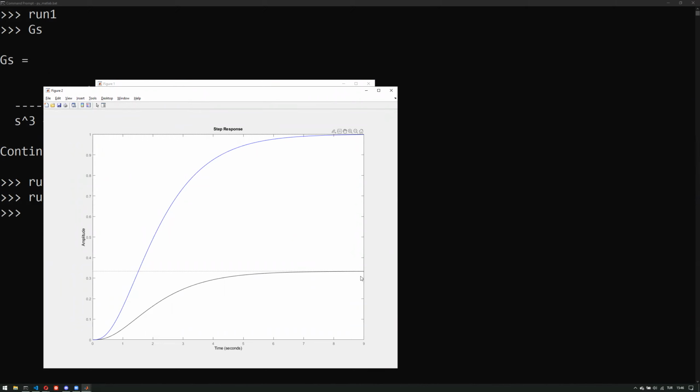But if I have an open loop control strategy, what I can do is say, okay, we need an amplification. Even though you provide me 1 unit of input, I will have a third of it. So if I triple it, the output should be exactly at that point. So therefore, let's multiply it with 3. So this is an open loop strategy.